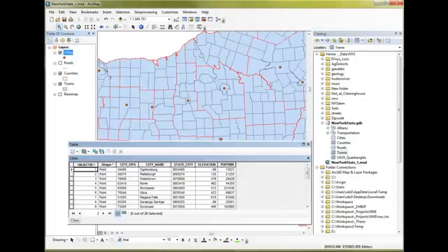Now this is the data that's attached to every feature in that feature class. So in this case it's cities, the layer's name, the table's name right down here, it's cities. If I click on any one of these, let's pick up Utica, should be visible, here it is over here in the far right. There's Utica. Notice I have a record here with data associated with a feature here. There's a one-to-one relationship for every feature in your feature class layer. There's going to be a record in your feature class attribute table.